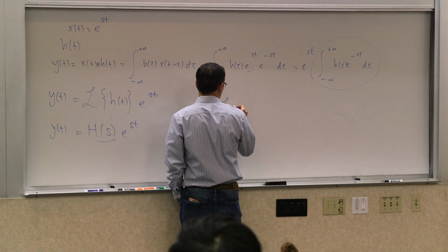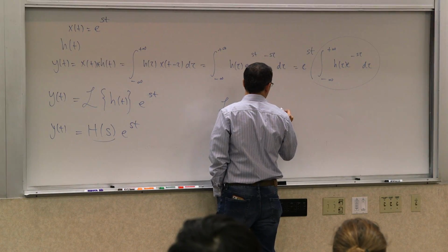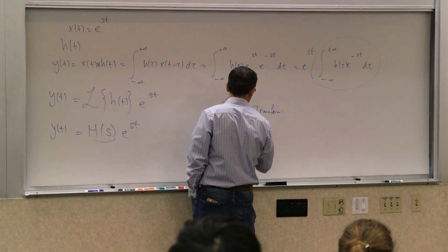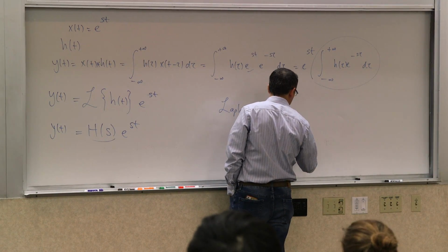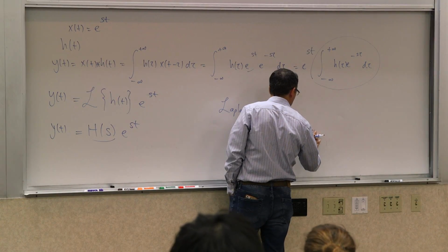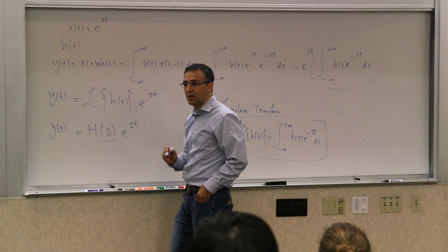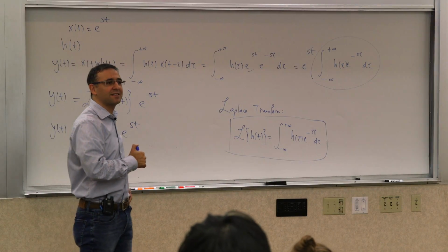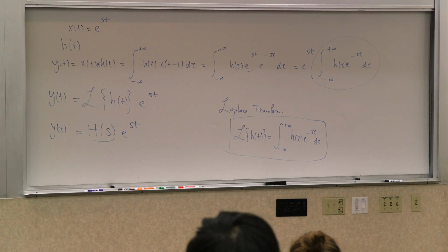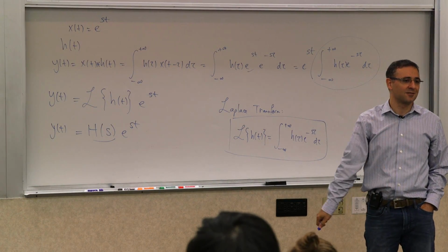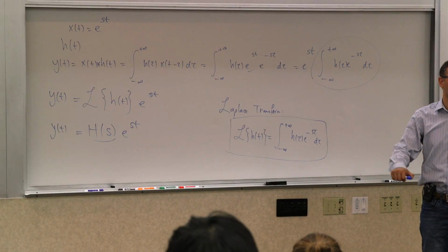So Laplace transform is essentially defined as this. So essentially the Laplace transform is evaluating the system response for an input that's e to the st. The weight of the forced response of a system with an input of e to the st is the Laplace transform.